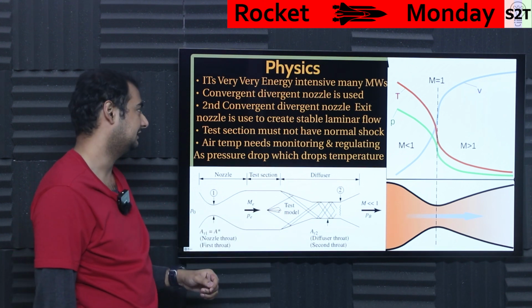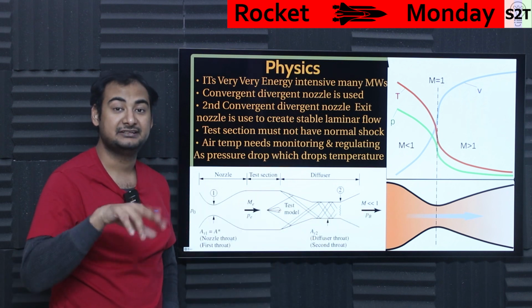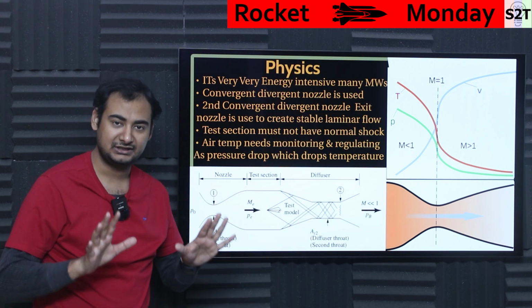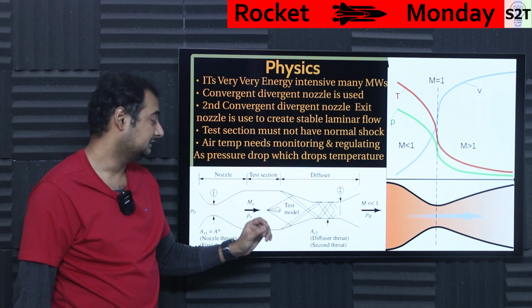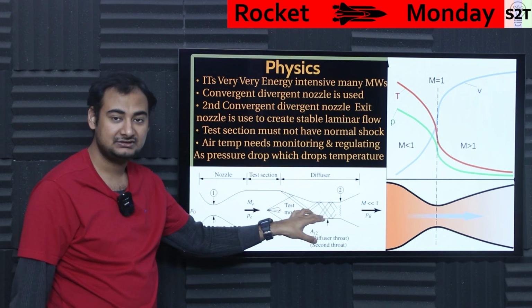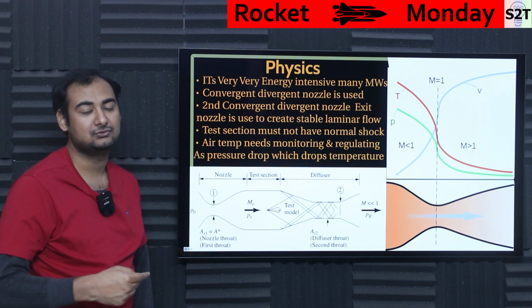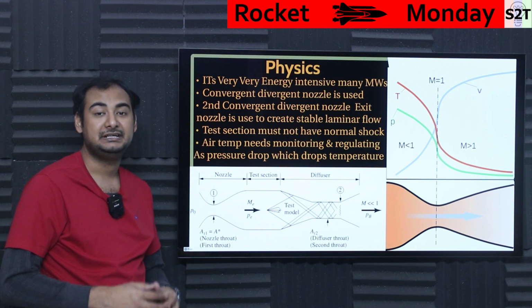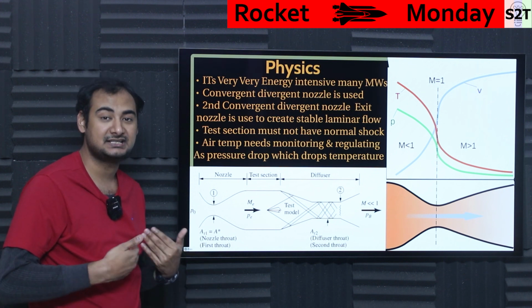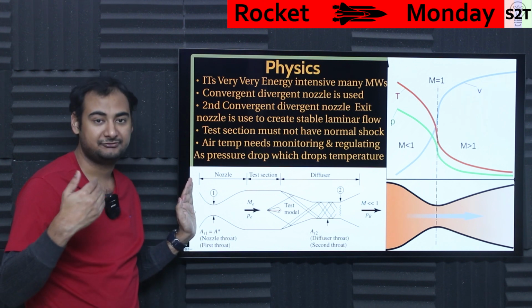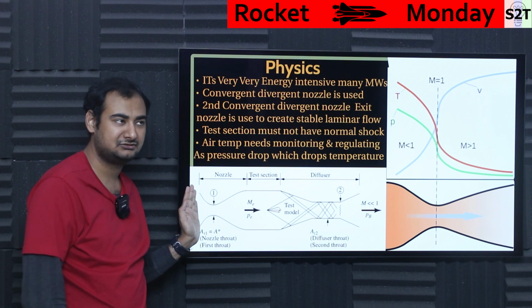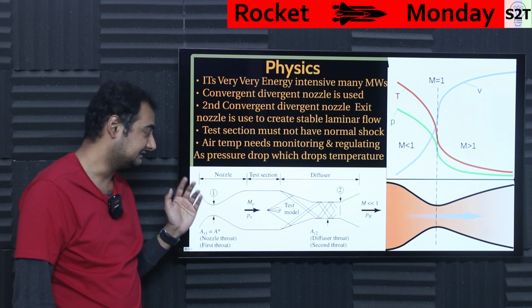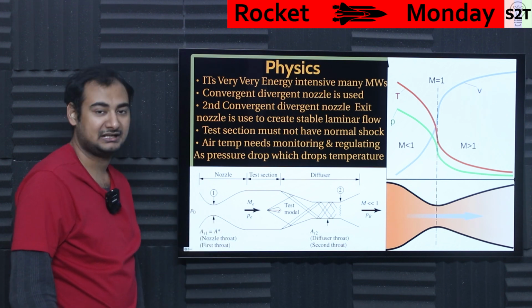a second diffuser section, which is basically this nozzle in reverse. Basically, you want air to relax, to phase out from super high speed to low speed. The reason for this is that if you do not do this, the inlet pressure requirement goes exponentially high. You want inlet pressure to be as low as possible so you can sustain that. So if you have to put, let's say, 50 bars of pressure here, that's acceptable. If you do not have this, you may end up needing to put, let's say, 500 bars here. At that point in time, that's very unmanageable, so to say.